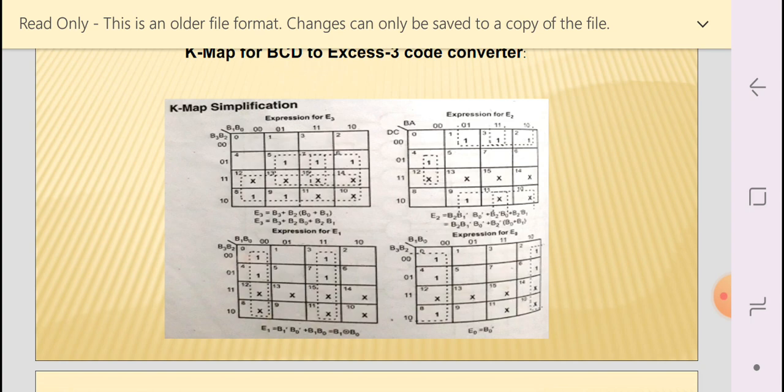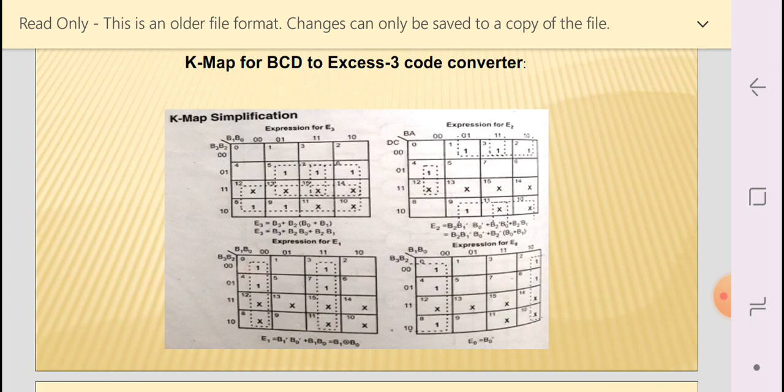Next you have to put the don't care. Don't care is also a fundamental thing of the K-map. Don't care means we do not care whether it is 1 or 0. We don't know whether it is 1 or 0. When we require a 1 against a don't care, denoted as x, we consider it as 1, right? So put the values from 10 to 15 as don't care.